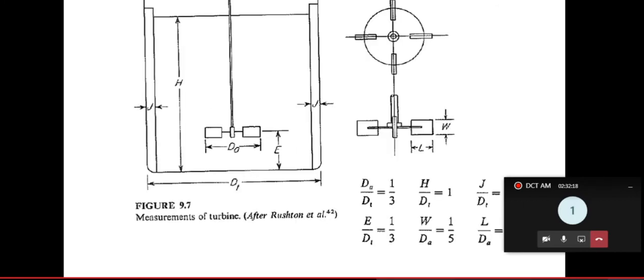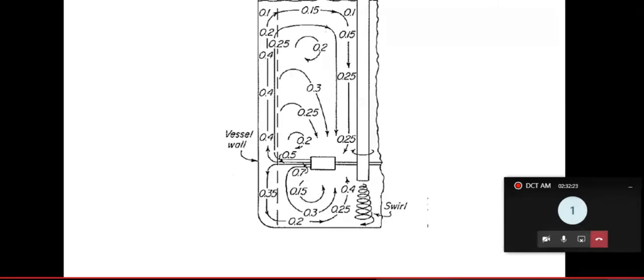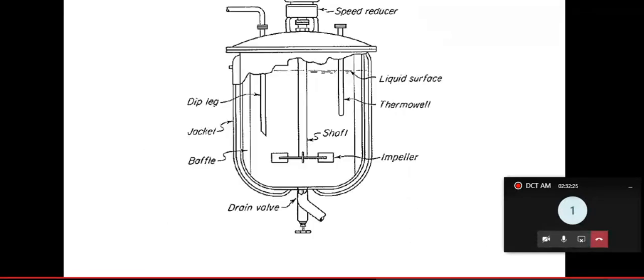Then dynamic characteristics are also very important. Now in this type of agitator, what type of flow currents are generated? Because of these flow currents only you would achieve the task. What was the task? The task was to reduce the power consumption and then reduce the time taken for the given process. How is it possible? This box is not doing any magic, but this box creates a magic called flow currents, which are established with respect to time. And in those flow currents only, the process of reaction, dissolution, maintenance, everything takes place, and then that will give your final product.